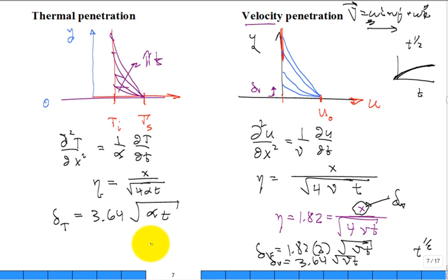You can treat a sheet of paper, as thin as it is, as semi-infinite if it's rolling very quickly through a machine and being impressed with something hot only for an instant. There's a lot of cases where we can use the semi-infinite approximation or solution for something that's really not semi-infinite. We're just going to be interested in the short time for the temperature change.